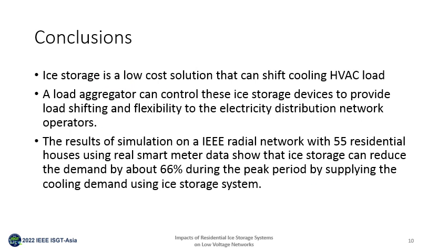In terms of conclusions of the paper, we show that the ice storage is a low-cost solution that can shift the cooling air conditioning load successfully. A load aggregator can use this flexibility to manage the distribution network performance, and the result of the simulation shows we can get a 66% reduction during peak period at this time.